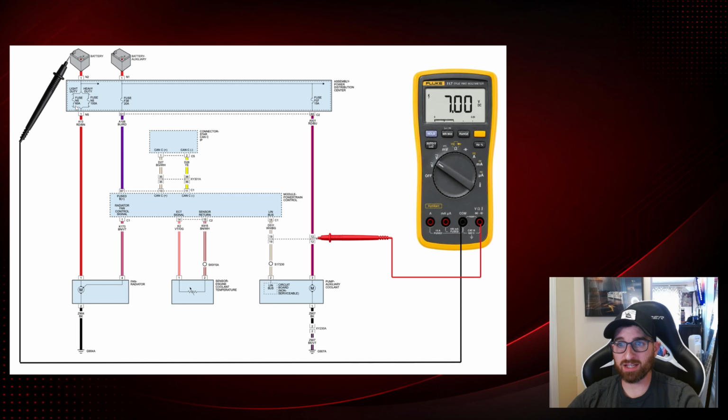You don't want to just take them off, because one of these does go back to the main battery, which is right here, N2 and N1. So two of these wires do go back to the batteries directly. So if you take those off and they grounded something, that won't really be the best scenario. So be a little bit careful taking this out. It does make testing a little bit harder, because now with all the batteries out of the car, I can't see what my voltage is here. So a little tricky, but I ended up getting access to this. We removed this and we got to this connector right here, C2 terminal A5.